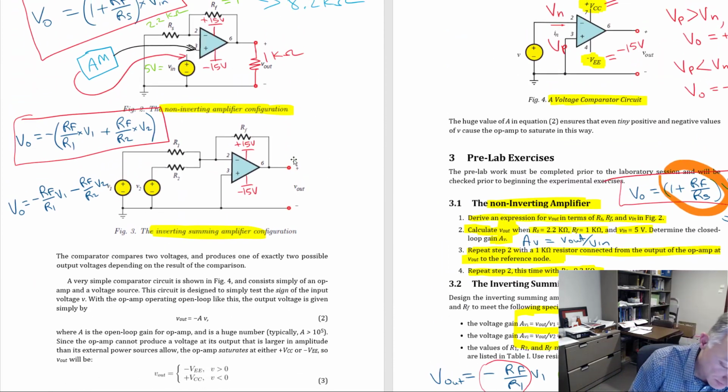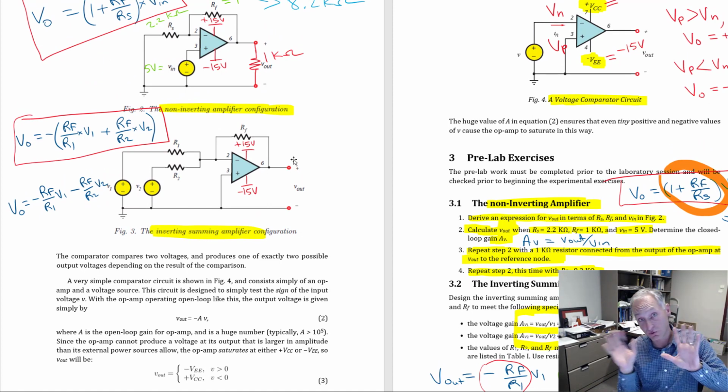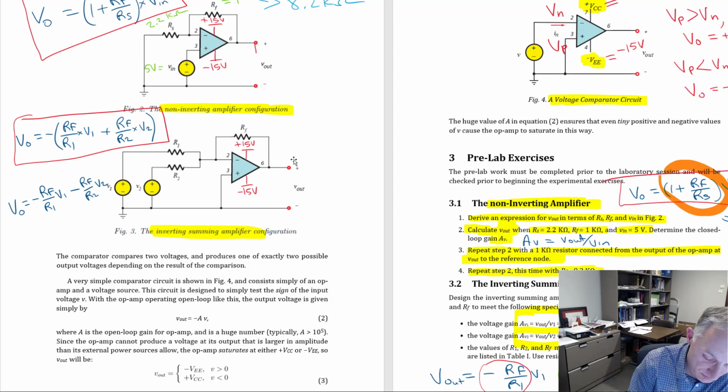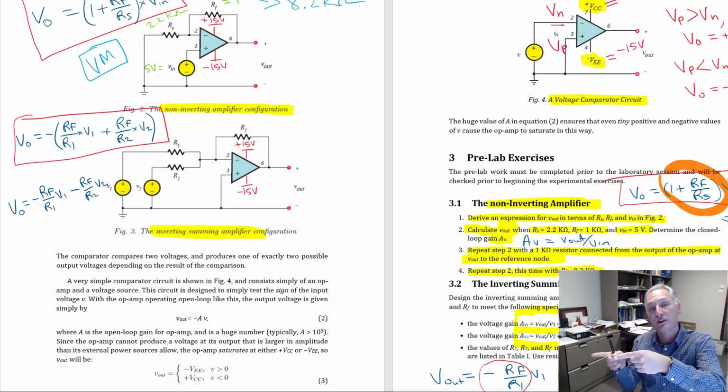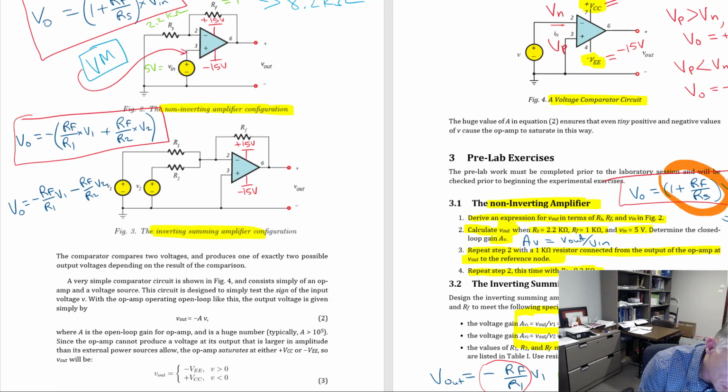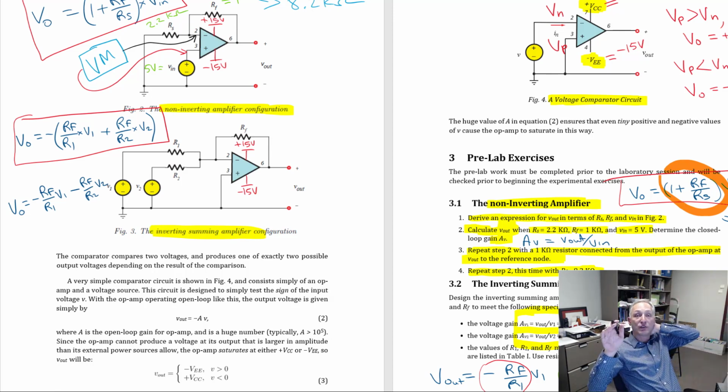Okay, so now I'm going to get rid of what I did. So I'm restoring the circuit back to how it was. So now it's like a working op amp circuit. And I guess at this point we're not going to have that resistor there. Anyway, so then I'm going to have my voltmeter, VM, and then I'm going to connect the voltmeter to measure the voltage between the two input terminals. So let's say my red lead would go to this input, and my black lead would go to this input. Okay, and then I'll measure the voltage.